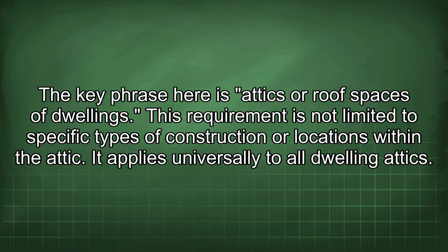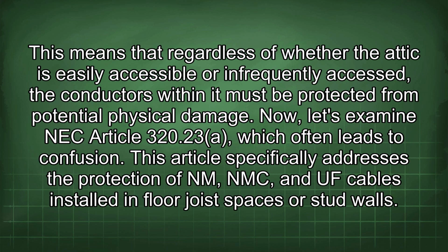This requirement is not limited to specific types of construction or locations within the attic. It applies universally to all dwelling attics. This means that regardless of whether the attic is easily accessible or infrequently accessed, the conductors within it must be protected from potential physical damage.